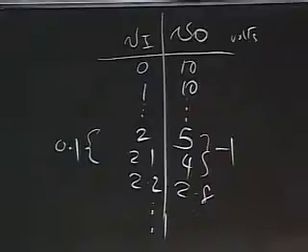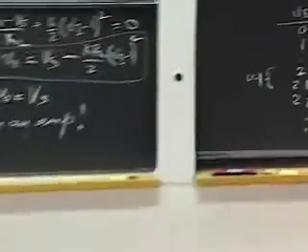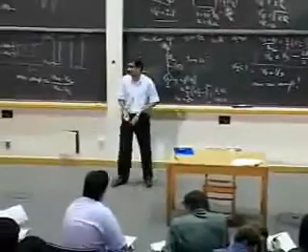So input went up by 0.1 volts, and my output kerplunked down by 1 whole volt. So a small change here resulted in a bigger change there, and that's the amplification that I am claiming here. Let me show you a little demo of a small device that I built involving such a dependent source.